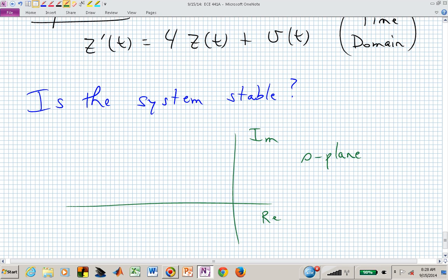It's just going to sit there and shake forever and ever because there's no damping. It's on the imaginary axis. Your damping term, e to the something t, is 0. All you have is an oscillator. If you now had poles on the imaginary axis, you would have an oscillator.